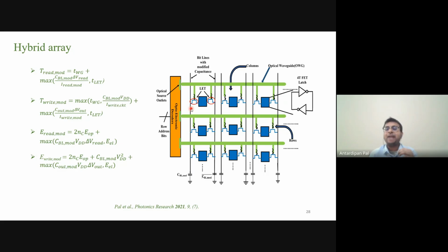SRAMs are directly interfaced with the CPU. They are extremely costly, so 2 megabytes of SRAM is a huge number. Believe me, 5 megabytes is crazy huge. 12 megabytes is more than huge. So we are talking about the megabytes range. Most computers have it in kilobytes, 512, 1 MB. So if you have a large SRAM array, say 2 megabytes, 5 megabytes, that means you have to have a large number of 6T cells horizontally and vertically.